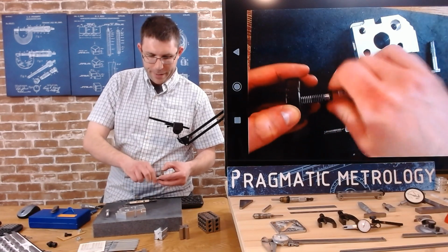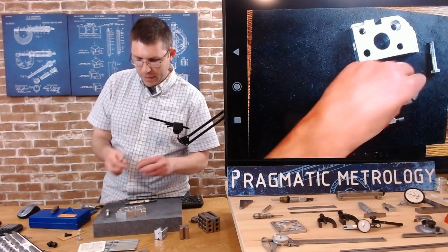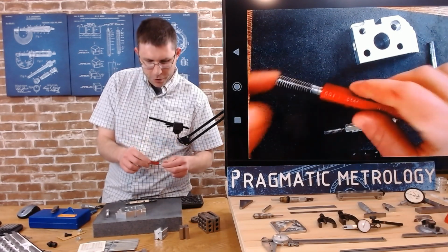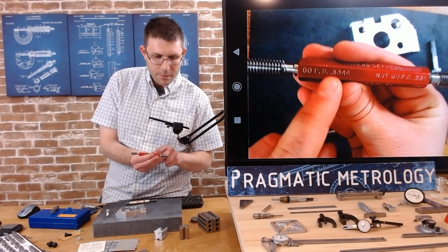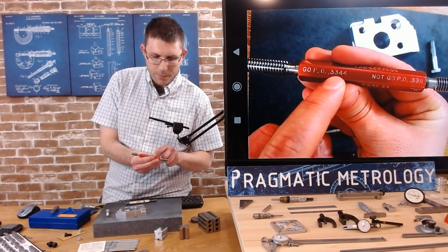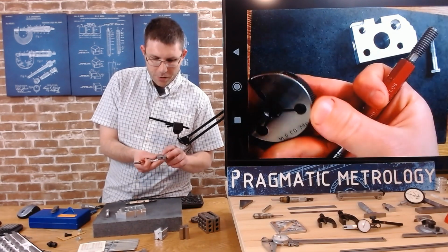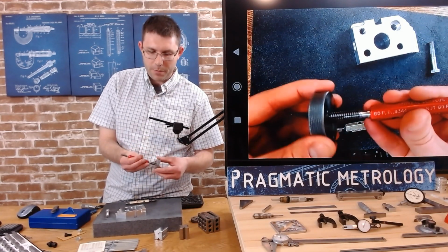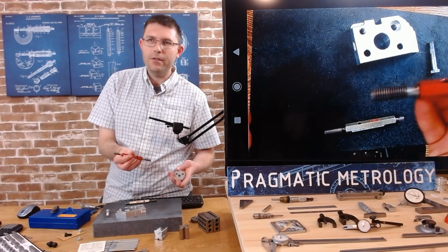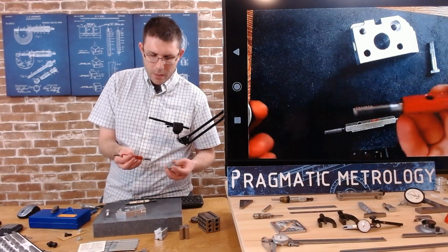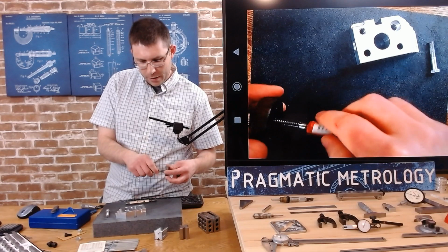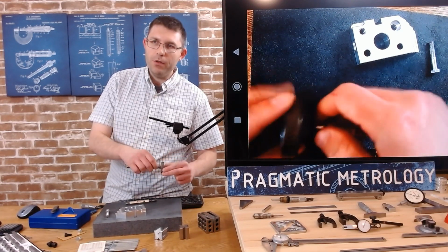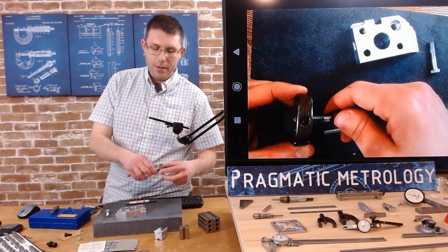The Go side has the same situation. Unfortunately, I have a little bit of a difference. I have a Go pitch diameter 334.4, and here I have a Go pitch diameter 333.7. So this is actually not going to fit on this plug gauge. They must be different classes. I did buy them separately, but it would work just like the NoGo side. You thread it on, you adjust the bolt until the tightness feels just right, and then you thread it off.